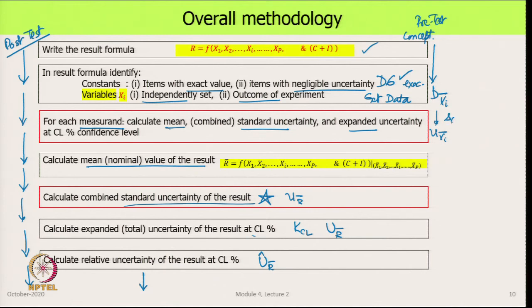If SXI bar were known from previous results or from experience or from a gut feeling, we could use that value also. And then we can continue with all of this process. And finally, we ask the question, is this good enough? When I set up my experiment, the mandate was that I want a result within plus minus something percent. How does this compare with that?